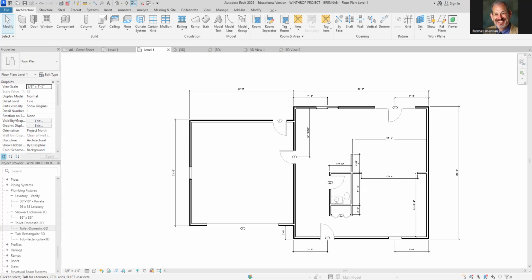Now, the next thing we want to do is make sure that opening is as it should be. So go here, and you're going to make a camera. Now go ahead and click it right here and take a look through there. Again, it's on the floor, like we talked about before. So let's review what we learned: we want to grab the wall opening, which is right here. Grab that, and we're going to make the top offset -1 foot, and it drops it down. You can see it. And then the bottom is going to be 0, like that. And that gives us that. And that is a wrap right there. I think that completes what we just went through.